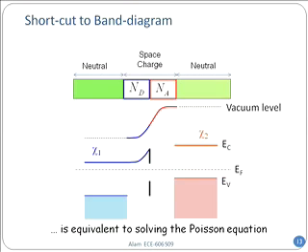Okay. Same thing on the right hand side. Copy the blue, copy the red, keep the chi2 distance the same, and bring it down here. Why have I done it for the valence band first? Because it's a p-type material. So I have to do the valence band first. And then, keeping the band gap, I will bring down this. You're actually done. This is the solution of the Poisson equation